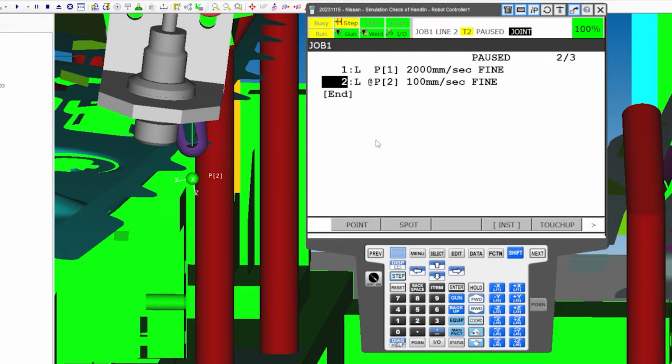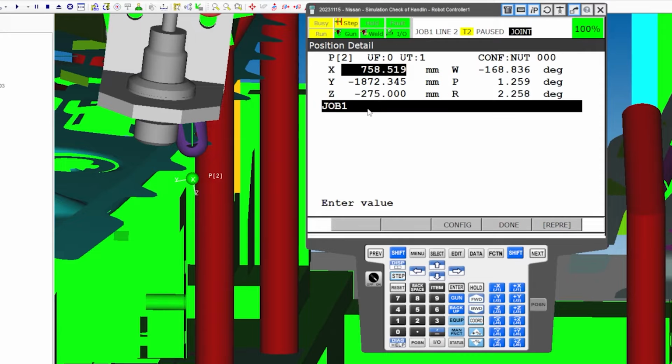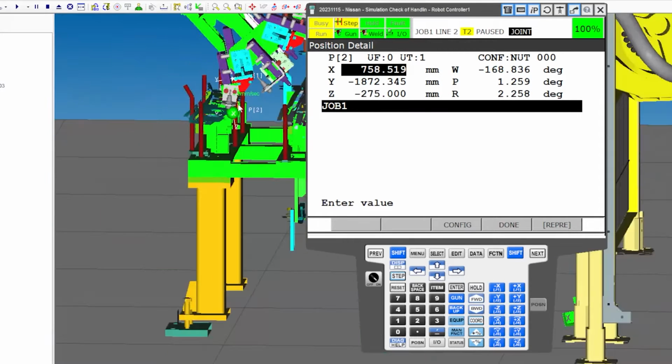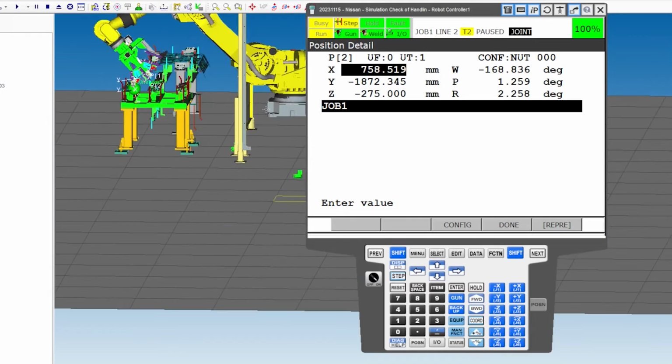By the way, notice this is really just a Roboguide issue, but see how I'm clicking my cursor around and it's going to the beginning and the end? It's because the shift key is held down. You'll make this mistake like 1,000 times. But yeah, so I turn that off and then I can go here. I'll go to position again. And then I need to zoom out from the robot to see where the base of the robot is.